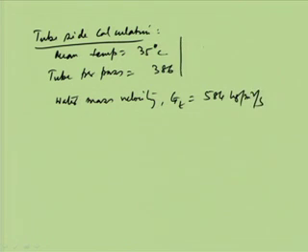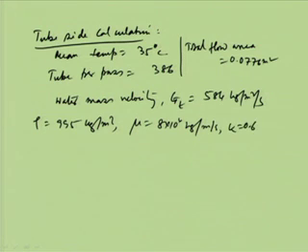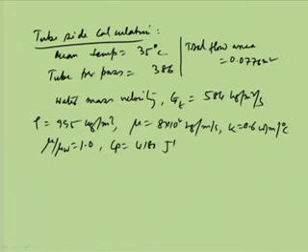It is based on this flow area, total flow area is equal to 0.0776 meter square. So, number of tubes into the area of each tube, and then rho is equal to 995 kg per meter cube, mu is equal to 8 into 10 to the power minus 4 kg per meter per second, K is equal to 0.6 watt per meter per degree centigrade, and mu by mu W is taken as 1.0, and Cp is equal to 4180 joule per kg per degree centigrade, and based on that we can find out velocity of water is